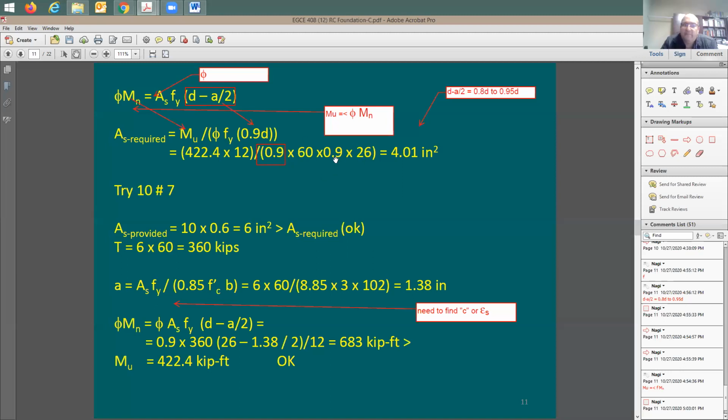But this is going to take time. I want to do this quick. This is what we usually do. I'm showing the actual, this is the reality, with just a calculator, in a second. When we do this, we call this 54 ksi. People are just used to it. Then you take the moment, multiply by 12, divide by 54, divide by another 0.9, and then just take a depth. And in this case, we just take a depth of 26.